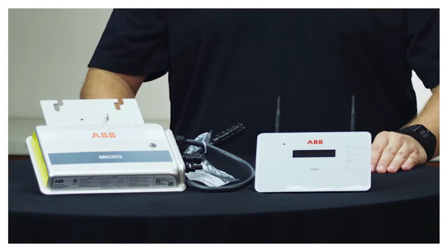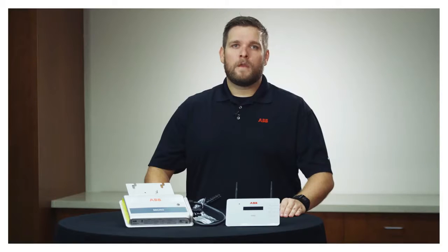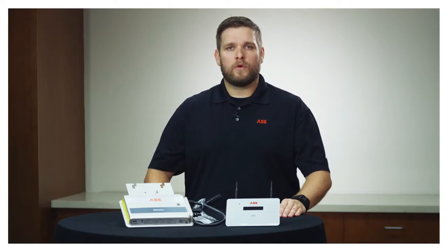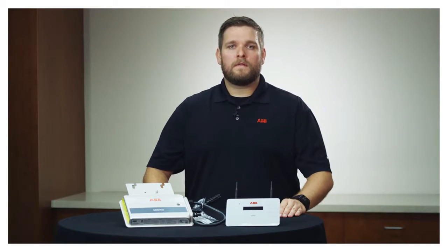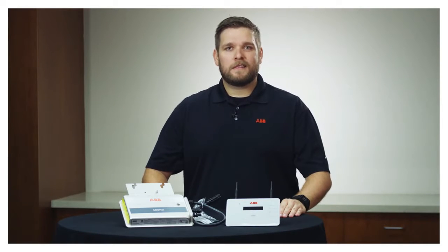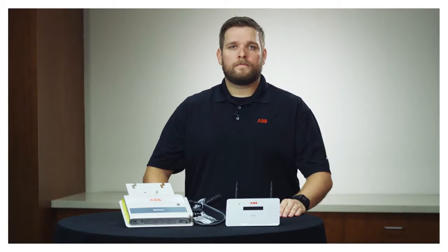Because the ABB CDD uses radio waves to transmit and receive data, it is important to assess this factor in choosing the installation position. Walls reinforced with cement and surfaces covered in metal, doors, shutters, etc., can drastically reduce the range of the device. Find a location for the CDD considering the signal strength degradation. Refer to the manual for more information.